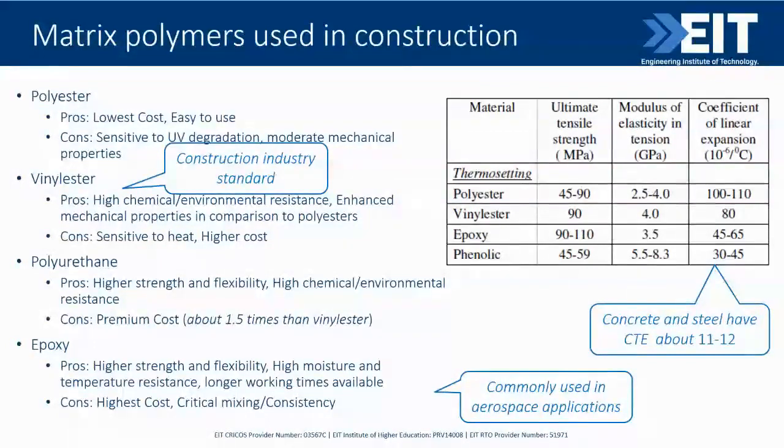This requirement should be coupled with adequate matrix shear strength. In addition, the matrix has to maintain chemical and thermal compatibility with fiber, so they will not affect each other chemically. And the matrix provides the color and surface finish for the aesthetic view, for any architectural elements.